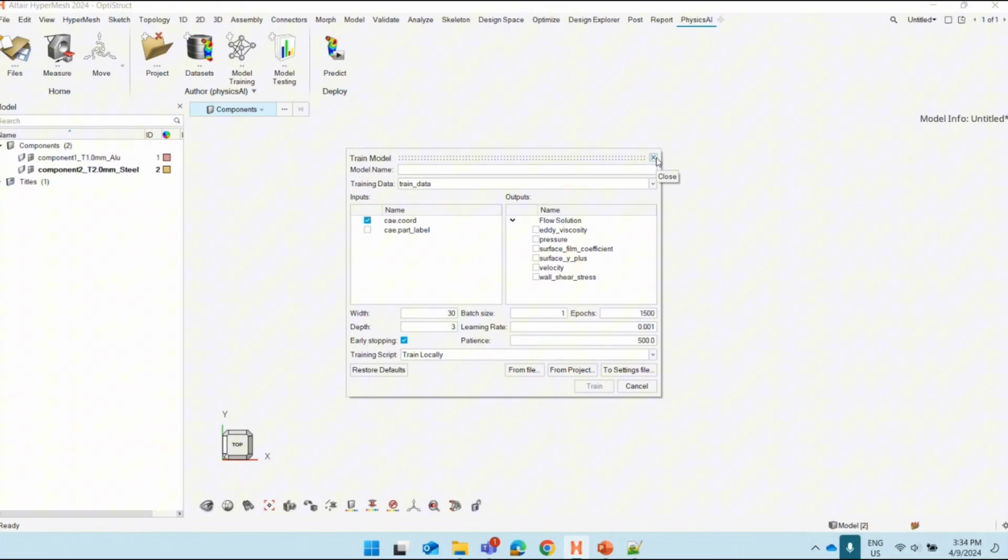No, you need to set up your model first, then run them. If before running you didn't set the component name, then there's no effect, because we are not changing the H3Ds anymore. So this has to be done before you run the initial simulation, before you get the H3D.